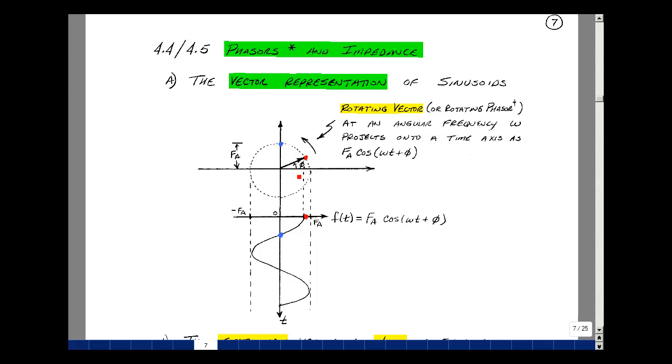If we do a problem with other voltages and currents, they'll have the same frequency as our original problem, because if we integrate or differentiate a cosine, we get a sine back, but a sine is really a cosine just phase shifted. We represent different voltages and currents by different phasors that have a length and an angle at t equals 0. Since they all have the same frequency, these vectors are rotating at the same angular velocity.